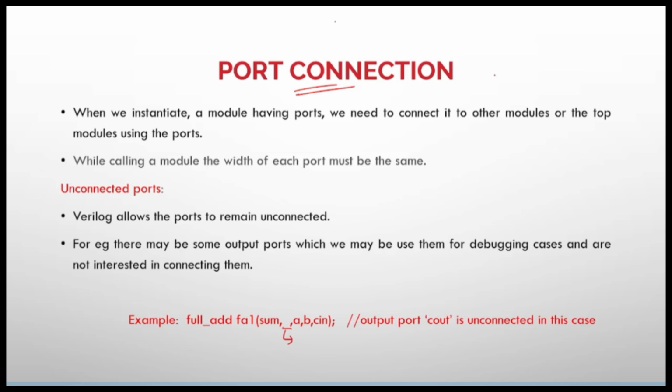Similarly in coding also, if you want to leave the port as unconnected, you can do that by leaving a space between the ports. Like if you see here, this is the full adder logic. You should have the port cout here. But if you don't want to connect this cout to any other element, you are just leaving the space here. Clear? You can do that.